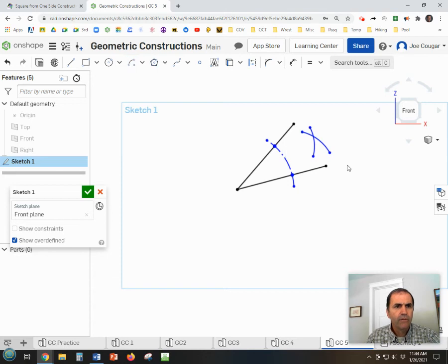Okay. That looks a little more like it. I'm not sure what I did before. Let's now make those equal to each other and hope the same weird thing doesn't happen. Okay, good. All right, we're going to put a point where they intersect and then a line. Now I'm going to do this a little bit different way. We're going to go kind of next to it, extending out, but then let's do a coincident constraint and we'll lock together that point and that line. So it goes through the middle of those.